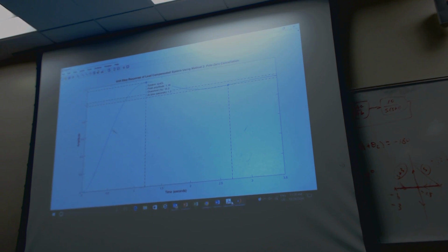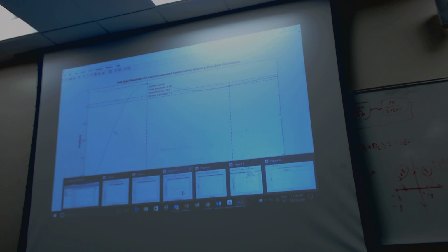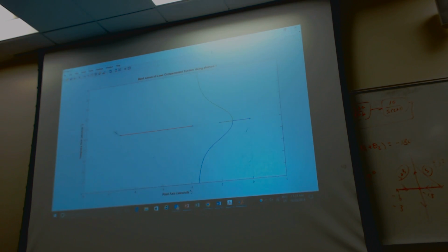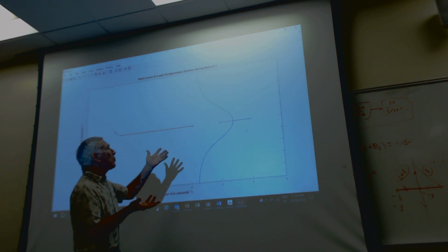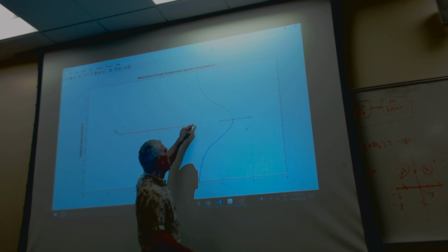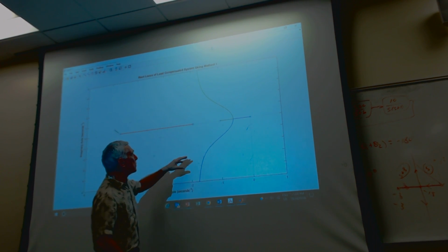And so I also just wanted to point out the other case. See, this root locus is the one that we will get using method one. And I'll go through it. But what you see is that there's no pole zero cancellation. See that the pole at -1 of the plant, and here's the 0, the compensator comes out to be like -2.